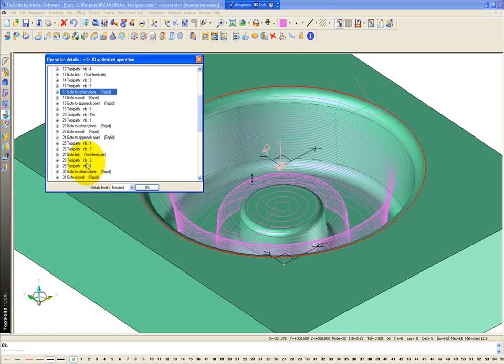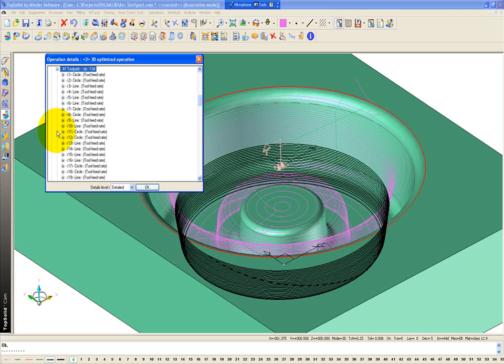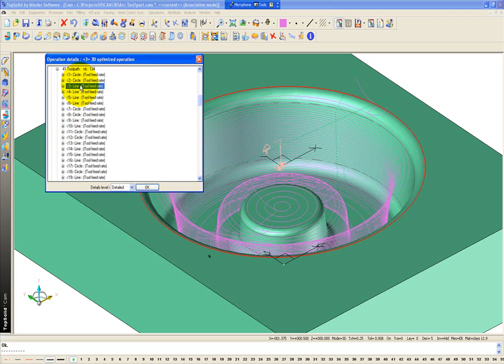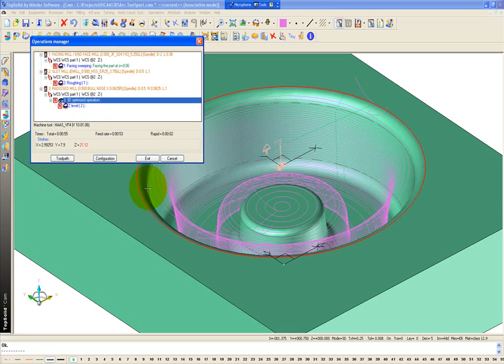If we go down to, let's go find ourselves some of the other toolpath. There we go. So here you can see we're cutting circles, lines, couple lines, circles. So it's a lot smoother toolpath. The best way to get the arc filter to work is to loosen your tolerance a little bit. So if you actually want to program it at like a 1,000th tolerance when you're running it on your machine, I would first change your Z-level tolerance to maybe a 0.5 to maybe a few tenths. And then this way you can loosen up the arc filter to 1,000, 1,500, something like that. You'll get your best results.